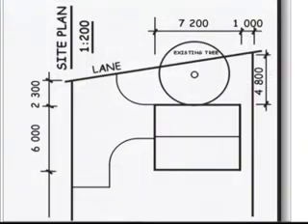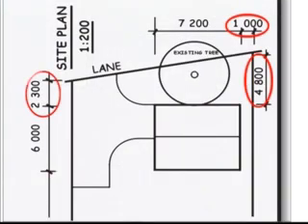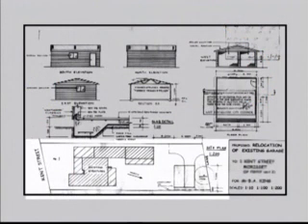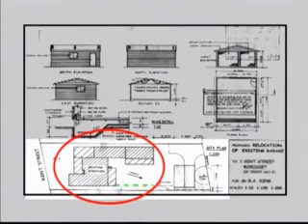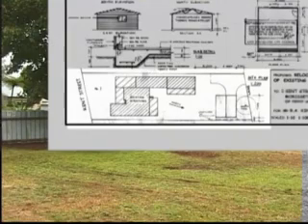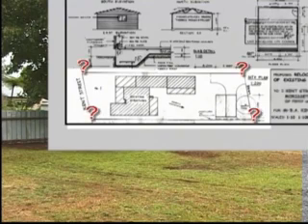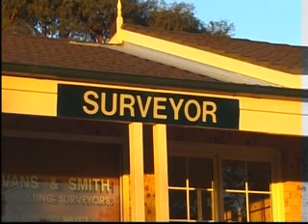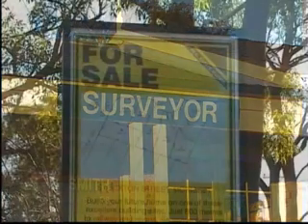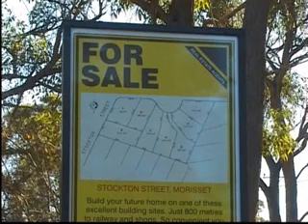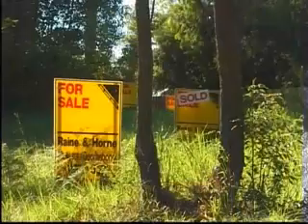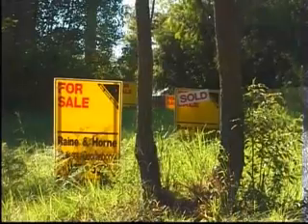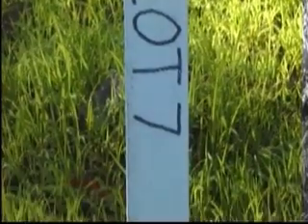The first step in setting out is to locate the survey marks for the building block. These will have been established by a registered surveyor to define the exact boundaries or outline of the block. On a new block, they are easily found. They are usually 50 mm square pegs driven close to ground level with a nail in the top. Measurements are made from the head of the nail.